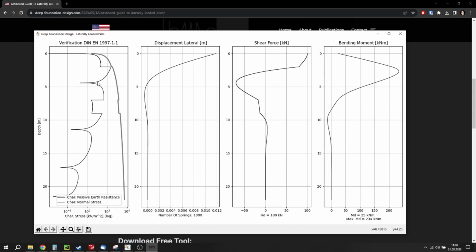At all these places where we cross the 0, 0 in the lateral displacement, obviously what we are going to expect is that we have 0 bedding, right? Because the pile is not moving against the soil, because there's no displacement, and then obviously we're not going to be having any sort of bedding there.